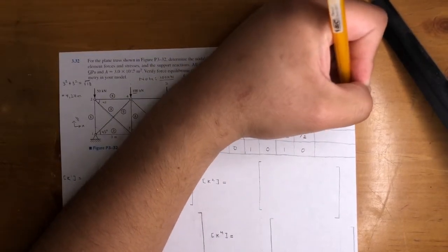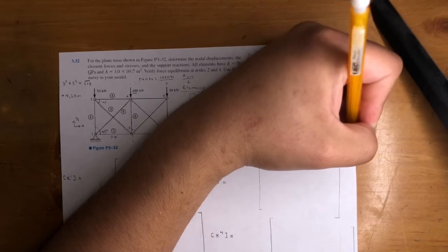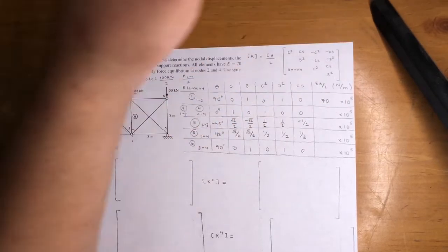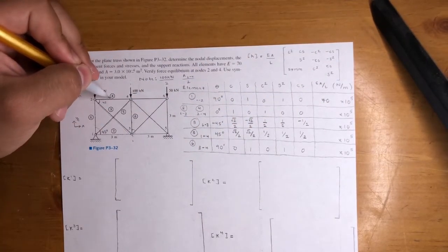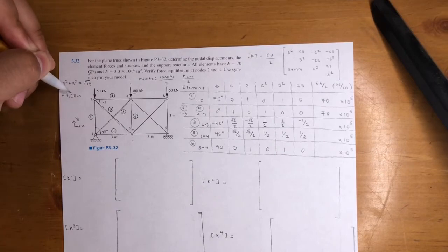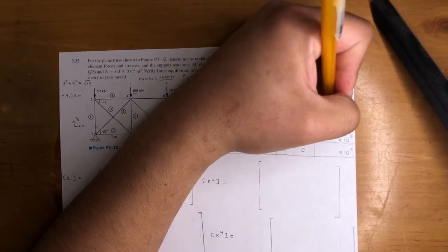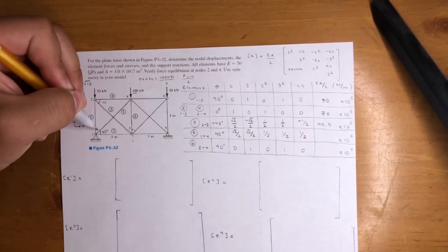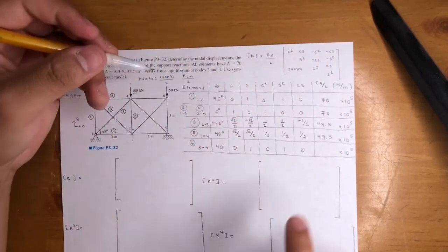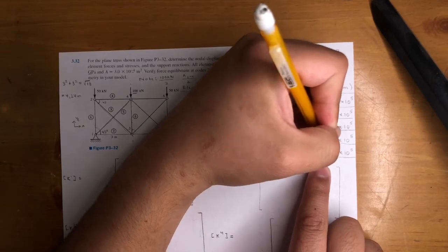Let me go ahead and write that here. So you can just focus on the big numbers. Okay, 10 to the 5th. So the first one was 70, right? 70 times 3 over 3, that's 70. Next one, 2 and 4, same thing, right? They're both 3 meters, so this one's also 70 for both of them. Number 3 is 70 times 3 over 4.24. That's going to give you 49.5. Same thing for element 5, right? It's also 4.24 in length. So that's also going to give you 49.5. Now this one's not 70. It's 3 meters long, but we get half of it. So half of 70 is going to be 35.